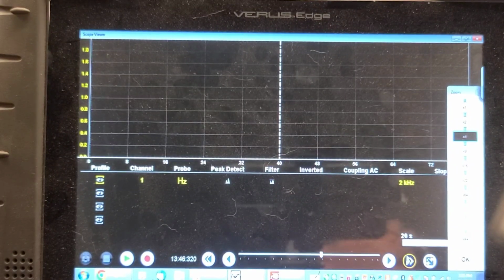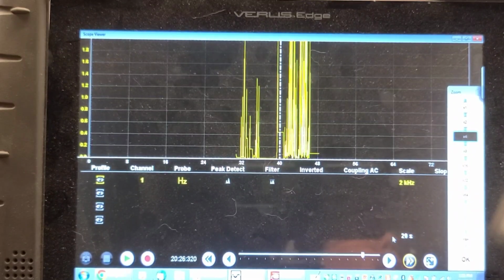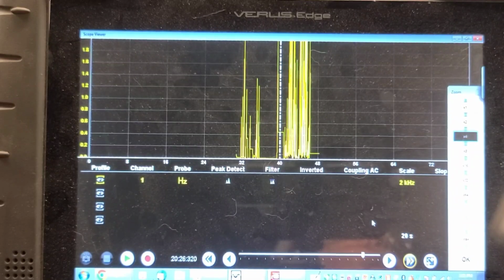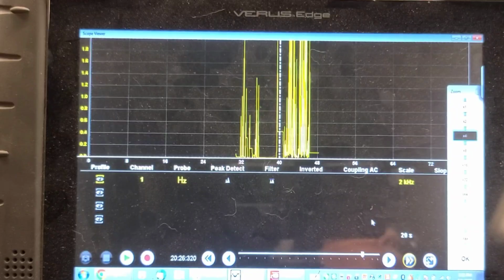Now, it's possible that the output shaft speed signal might not be displayed if it's not in drive. Because think about it, it wouldn't be expecting a speed signal if it's not in a forward or reverse gear. I had it in park when it was idling. So I think that output shaft speed sensor is failing. It's a Hall effect and it could break down.